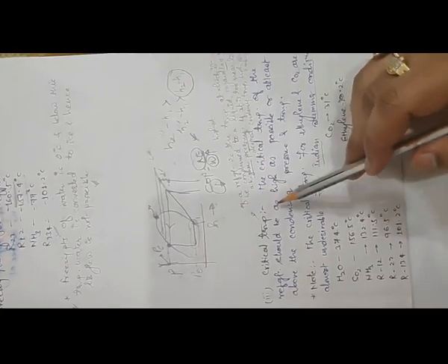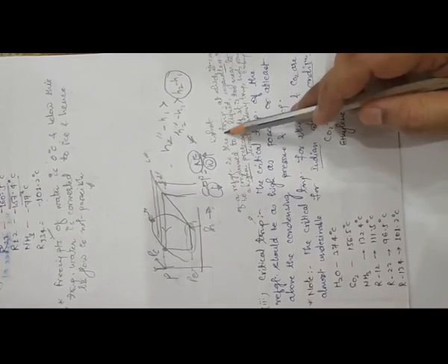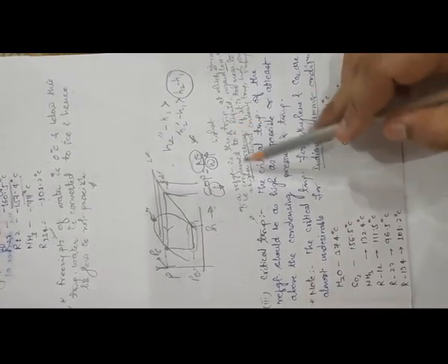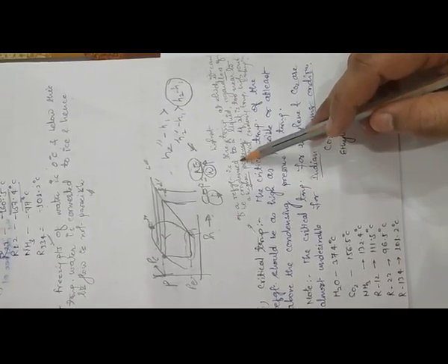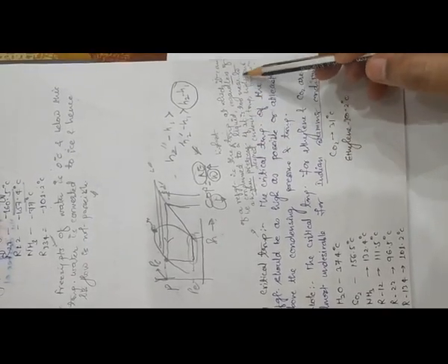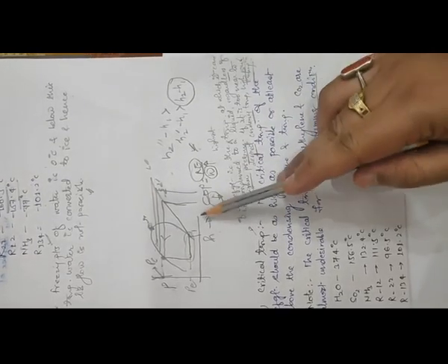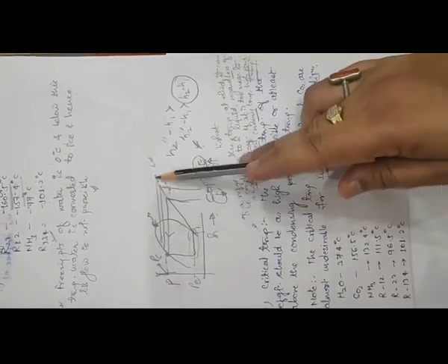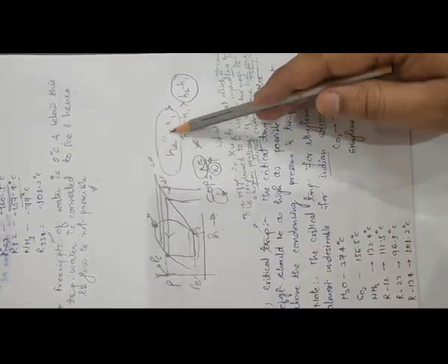Also we can see the critical temperature of a refrigerant is the highest temperature, listen carefully, at which it can be converted to a liquid regardless of its higher pressure. If it is too near to the desired condenser temperature, there is always higher power consumption. As I already told you, if it is near the critical temperature, there will always be higher work input to the compressor, and again it will result in higher power consumption.